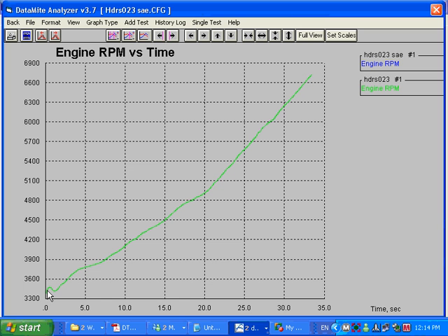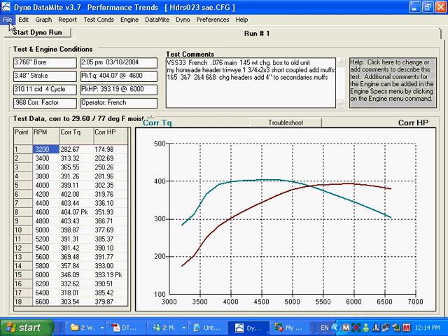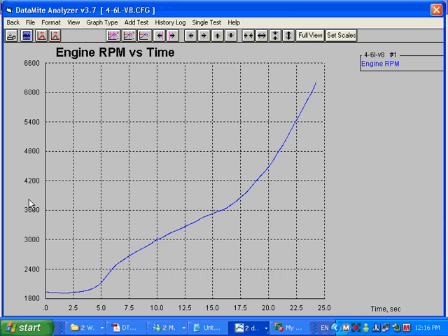Here's the acceleration rate. And you can say, oh, this is a very slow test. Yep. I'm going to pull out a test that's got a faster acceleration rate. Here's one of our example tests. This is the 4.6 liter V8. You can see it takes 20 some seconds to do the whole run, but from here to here, it only takes about 5 seconds to go from 3,600 up to 6,000 RPM. So a fairly high acceleration rate through that part of the curve. And this should be producing less power than if you had a slower axle during that part of the curve.